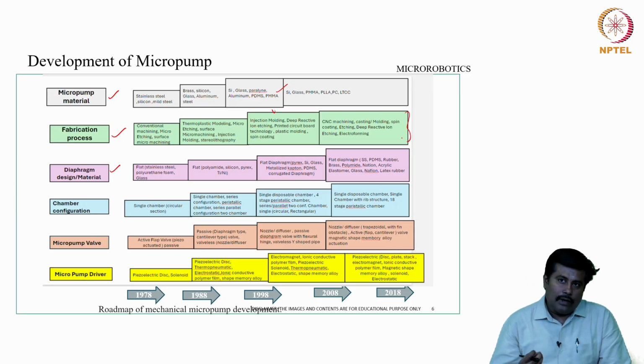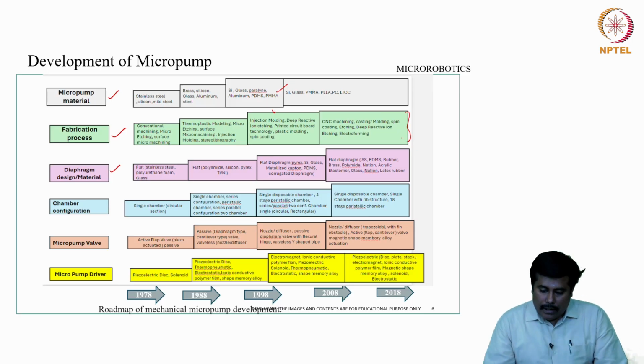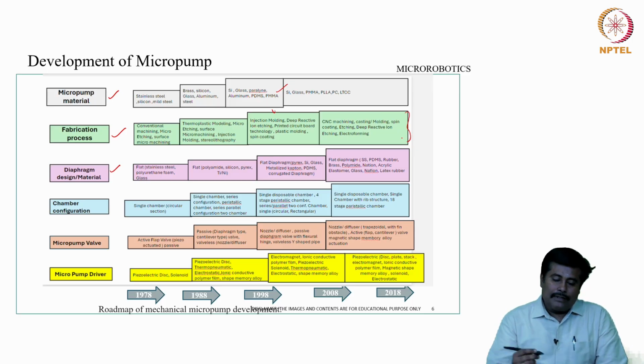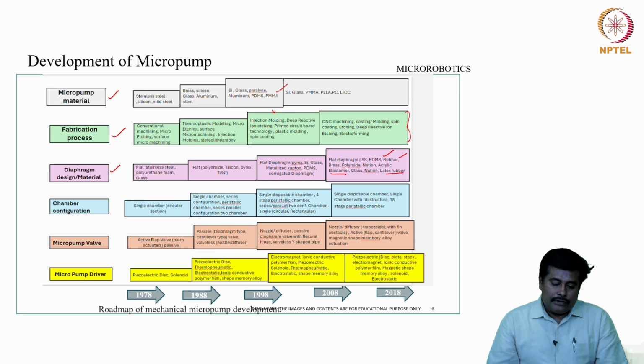In certain cases we can also have metallized Kapton based diaphragms. In addition to this, there are certain elements with direct relevance towards diaphragms, like PDMS, rubber, elastomers, latex layers, etc., which can be efficiently deployed for diaphragm related applications.